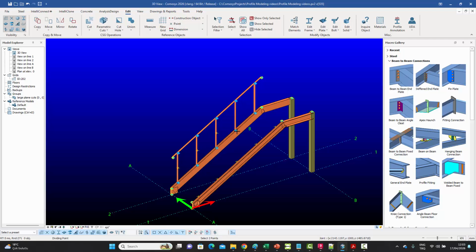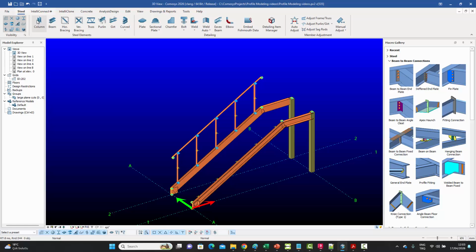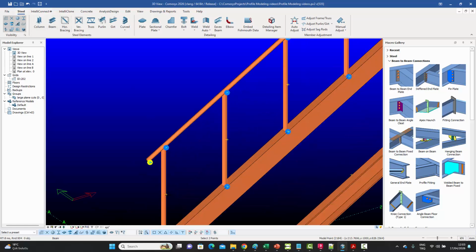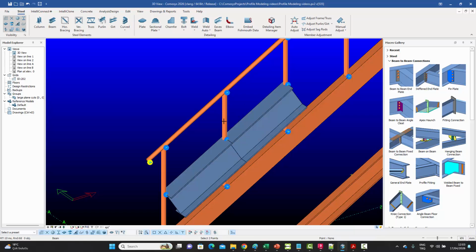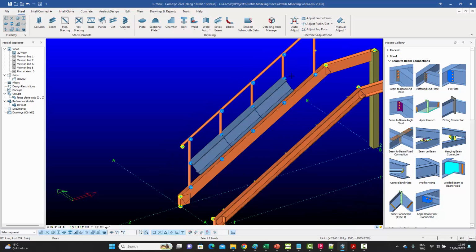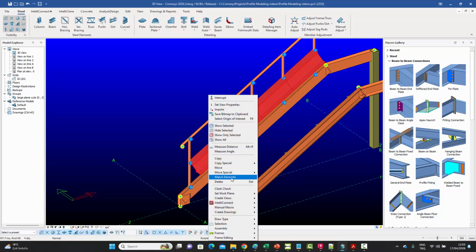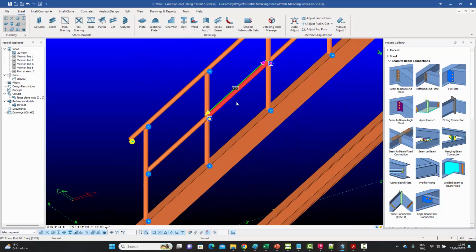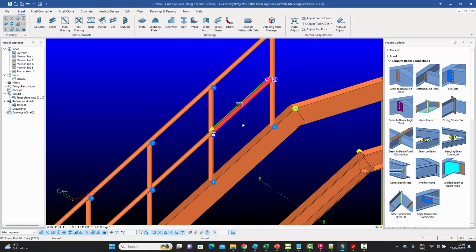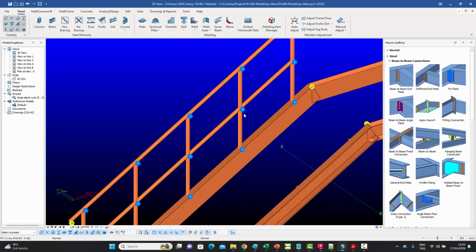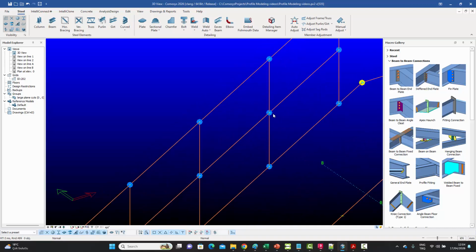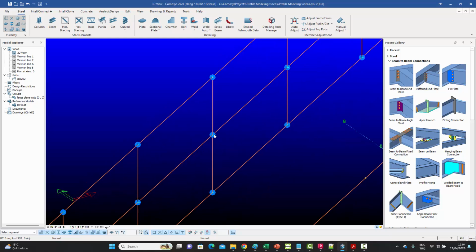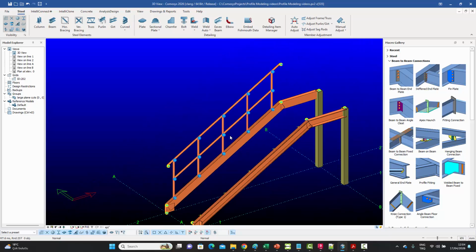In fact, the midpoints are already snappable, so I don't really need to do this. But what I can do is go in and enter my knee plates, or knee profiles, if you will. Then I just need to select them and say match elements to the top one, which is going to be a better idea. Yeah, there you go. So now we have these ones entered, and they're located perfectly. And once again, the moment I want to check everything in line mode, I can just click and see whether I've made any mistake, and everything is connecting, and it's also correctly positioned as well.